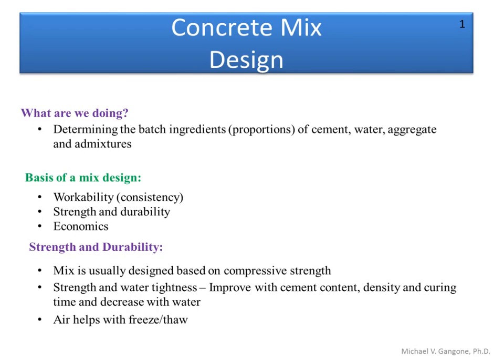When it comes to durability, water tightness is important, keeping the chemicals and some of the environmental effects out of the concrete, from permeating into the concrete and causing some disintegration or deterioration to occur. Of course, freeze-thaw is also a big part of durability, and having an air entrainment admixture helps a lot in improving the durability of concrete, especially in areas that have a lot of freeze-thaw effects.